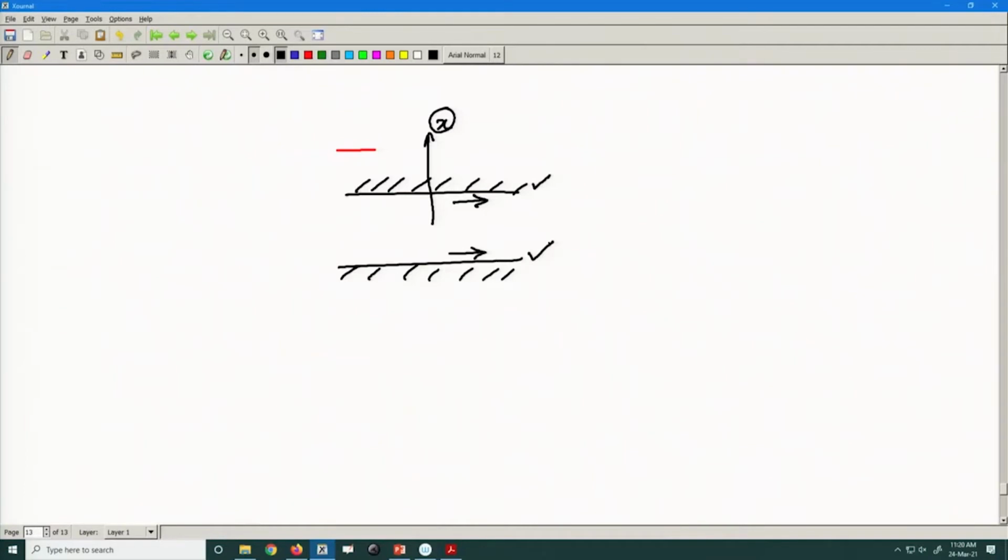So, to satisfy the perfect electric boundary condition, here we have the perfect electric condition, here we have the perfect electric condition. So, the choice of the potential function is going to be dictated by which choice, either sine or cos, but not both, will cause the tangential electric fields at these two locations to vanish.